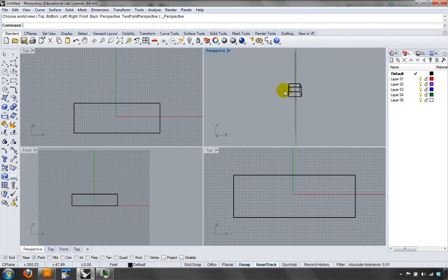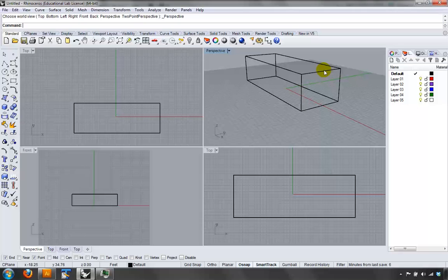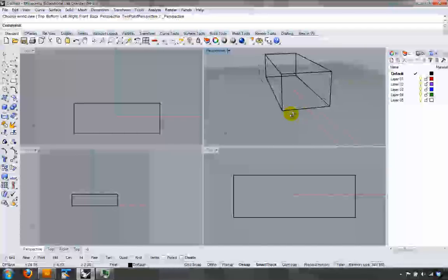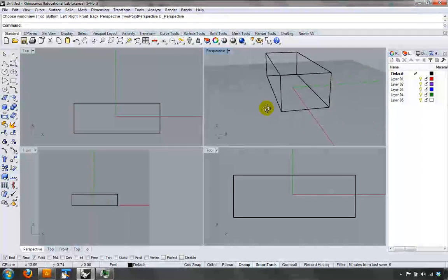Note that the perspective view changes the drawing plane to whatever the last orthographic view is. We'll talk about this more later, but just in case you're confused as to why that is, that's why. If I went to perspective from a top view, you get what you'd expect, which is that the ground plane, which is really just a grid for reference, doesn't actually exist. It doesn't render or anything. It's just the plane from the top view. So moving the camera, the viewport around is really useful.